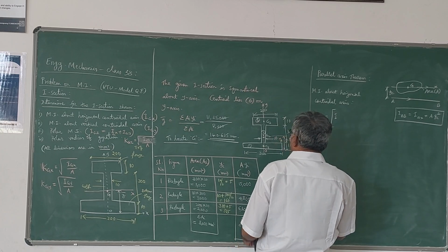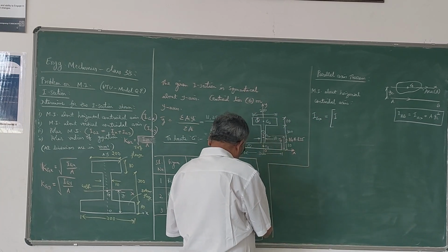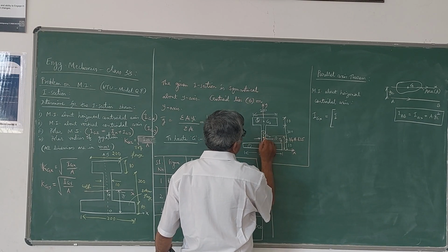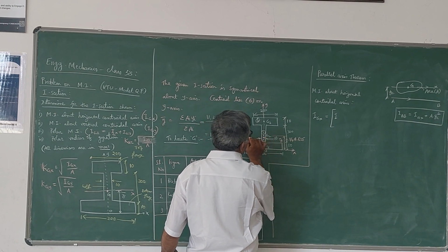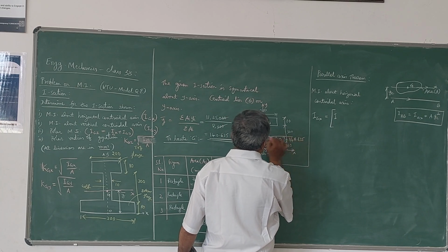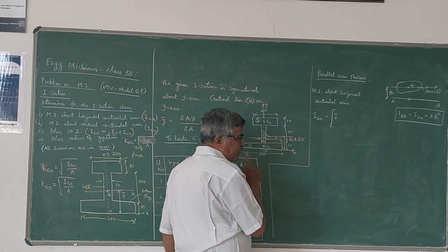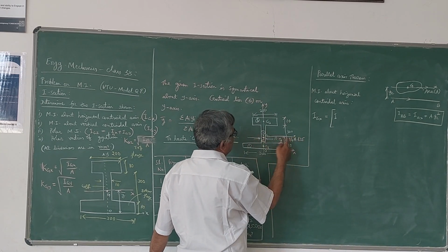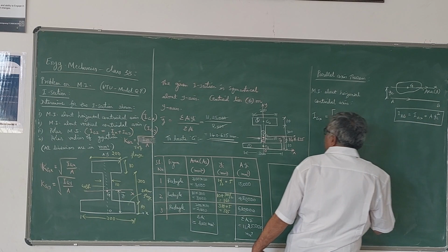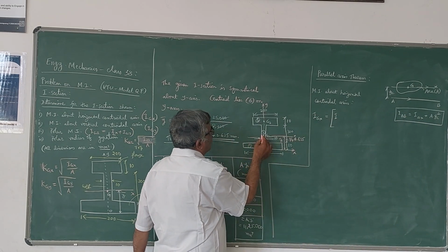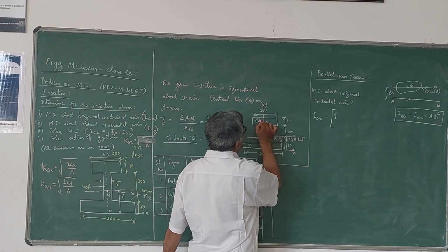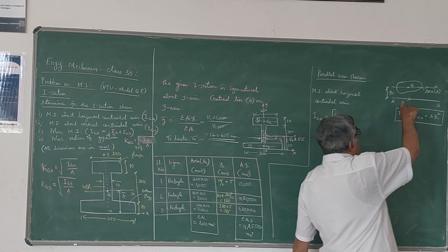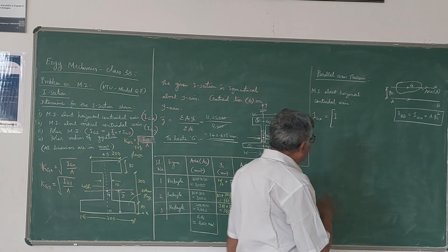Please note that if I draw an axis passing through this G, this becomes your AB axis. Please be careful here. So this GX axis becomes the AB axis here. Whatever axis we are going to draw for each individual simple section, they become the centroidal axis for the individual section. That means here I have shown for one figure there are 3 rectangles.